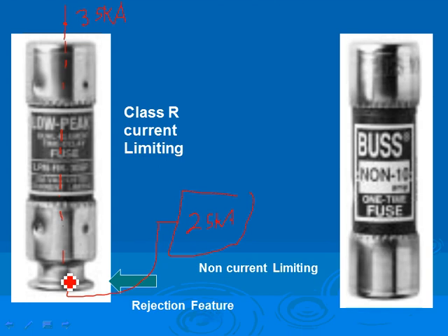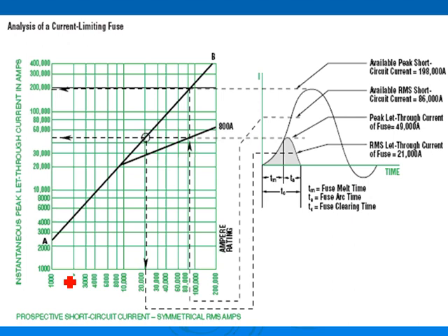Who cares? After you have a short circuit, three-phase, the highest short circuit that could be encountered in this piece of equipment, the only thing that's going to be seen, the 35 will be cut enough that it will not see more than 25. And there are a couple of tables that you can use to size current limiting fuses. Here's a great application of current limiting fuses. How many of you guys have seen this? Raise of hand. No? Or is it too late now to think, Chad? Look at this. This is right here at this point.